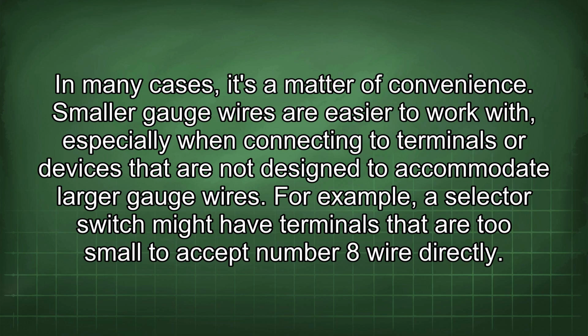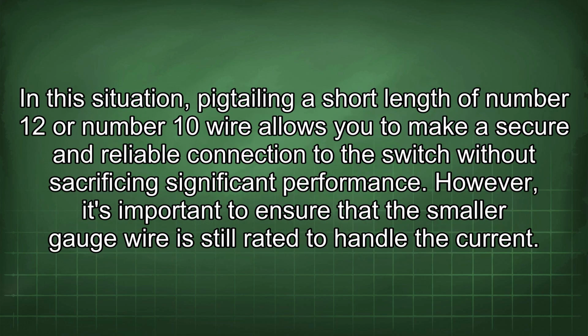Especially when connecting to terminals or devices that are not designed to accommodate larger gauge wires. For example, a selector switch might have terminals that are too small to accept number 8 wire directly. In this situation, pigtailing a short length of number 12 or number 10 wire allows you to make a secure and reliable connection to the switch without sacrificing significant performance.